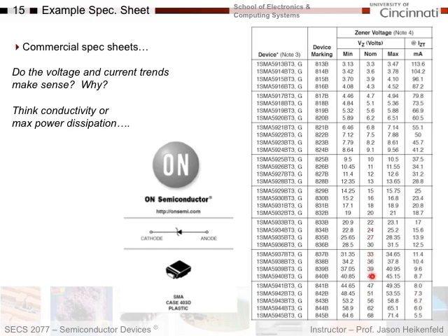But I do understand that if your breakdown voltage increases, then the maximum current it can flow should go down, because current times voltage is power dissipation, and these things can only dissipate so much power. So your power dissipation has to stay somewhat consistent, because this thing essentially will turn into a puff of smoke. And so you can get a higher breakdown voltage, but then the Zener current, when it breaks down, has to decrease, otherwise it will turn to a puff of smoke.